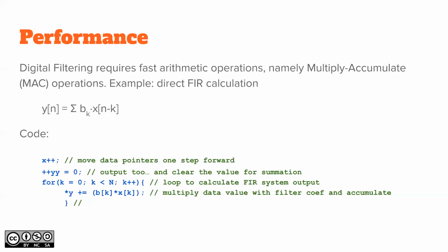Which basically means if you want to make a high performance system, meaning a really fast control loop, which doesn't usually make any sense, but anyways, if you want to do something fast on that processor, then you need to do everything in integer arithmetic.